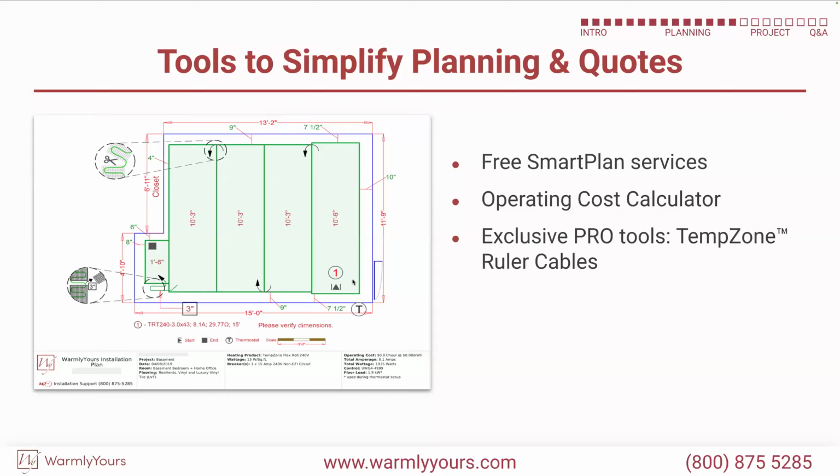So that's what you're going to be looking at on your plan. Also notice we're not heating every square inch of this space. We're pulling away from the walls. Part of the reason we heat away from the walls is no one ever stands there. No one ever stands, this is a lineup, stand right up against the wall. You don't do that at home. You do that at the police station, but you don't do that at home. So there's no need to heat the floor there. Right. So that's why we pull it to where you're going to be walking.